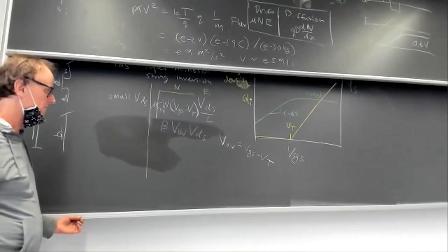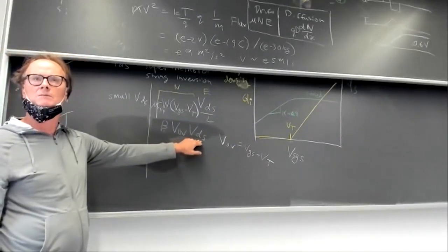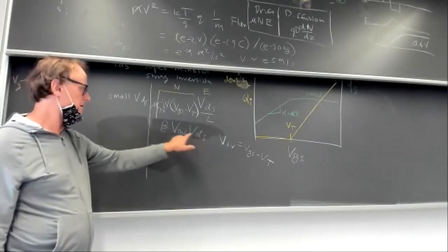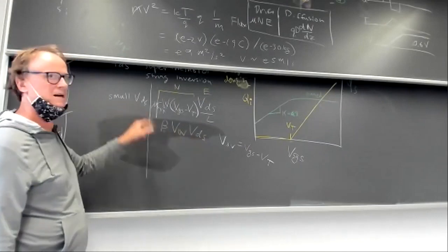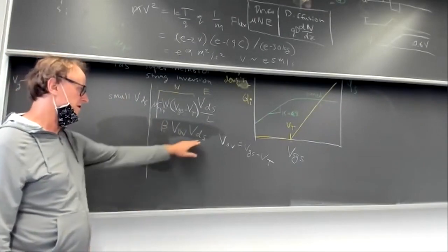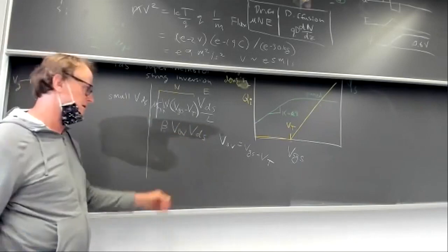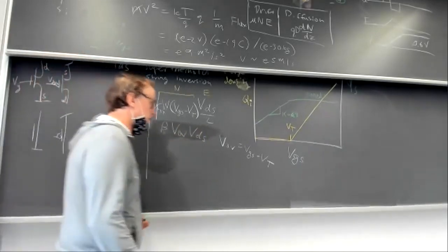That's the first thing you're going to measure. You're going to set a small drain source voltage, I think. Is that right, Junred? Is that the first measurement? The small VDS drain current. Yes. So you're going to set a small drain source voltage on your NFET and sweep the gate voltage and just measure this. And what you should get is exactly that curve.